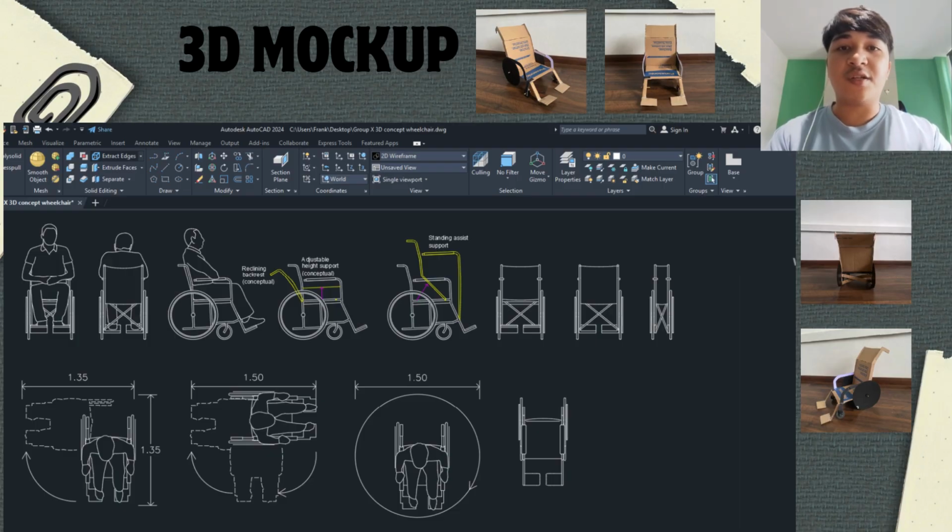The first modification is the reclining backrest, as shown in the side view and labeled in the drawing. The backrest rotates about a pivot located near the seat back junction. This recline is represented conceptually using an inclined backrest position. The recline range is intended to be suitable for elderly users, allowing comfort and pressure relief while maintaining postural stability. This feature is particularly beneficial for long-duration sitting.